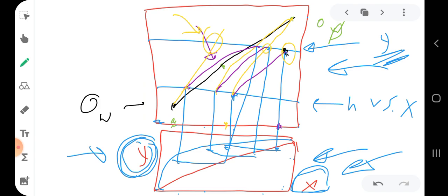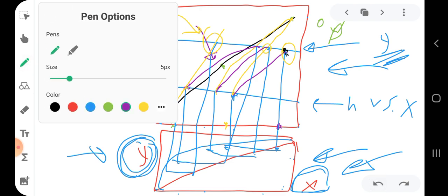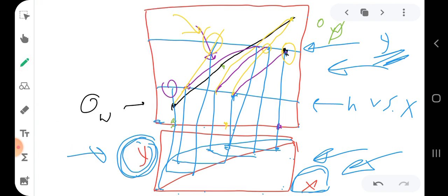I have this point. Okay, so I move here until the 45-degree line, then I move to the equilibrium curve, then I move up, so I reach here to the liquid curve. Okay, again I connect this point with the starting point where I move, yeah, here, this point. Okay, so I connect them.